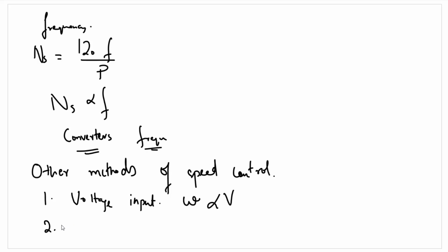There's a limit to this, however. We cannot reduce the voltage beyond a level where our current increases beyond the rated current of the induction motor. Such a case will actually cause the motor to burn out.